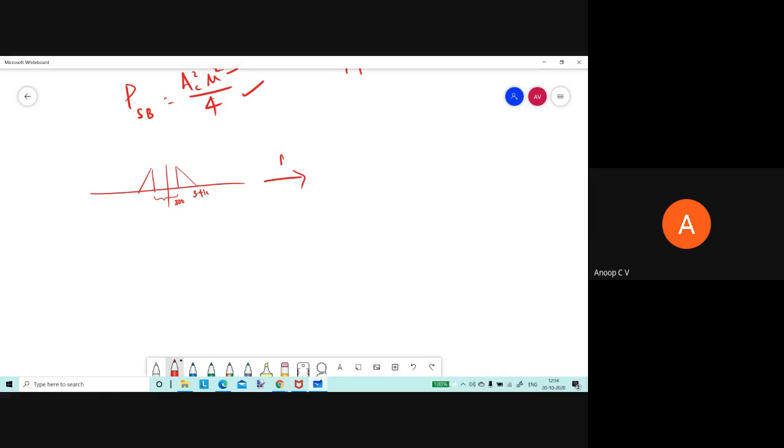If I use a carrier fc, the SSB spectrum will be something like this. This entire spectrum will be shifted right by an amount fc, and there will also be a negative part. So this is how the spectrum will look; it will be centered around fc. If you consider this as f minimum and this as f maximum, what will be this spectral separation? If you inspect this, you will get to know the spectral separation will be 2 times f minimum.